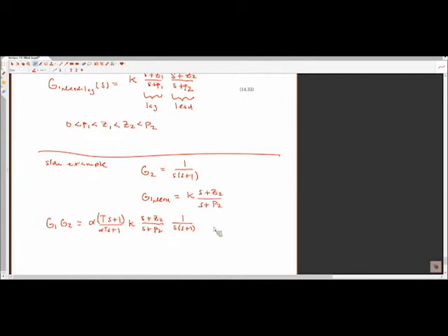Because you have to include the lead controller, it definitely has dynamics, and it definitely has a gain to it, and you want to make sure that you're reflecting that when you design your lag controller. Step 0 of the lag controller is okay. You are already happy with the transient response, and if you required a lead controller, it means that you had to do some work to become happy with that transient response. So you have to include that in there.